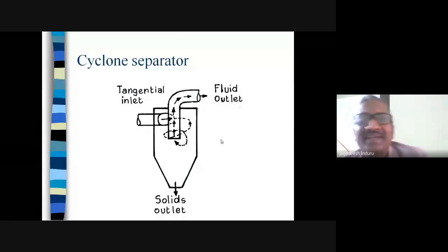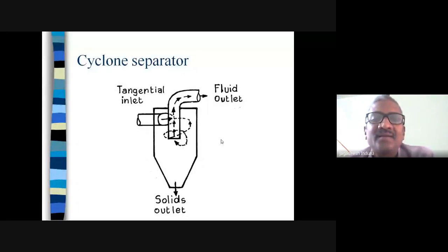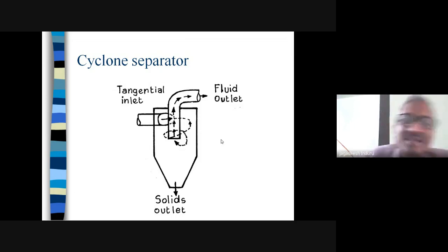The advantage of this equipment is that it does not have any sieving surface like a screen or a sieve. That is the reason it won't have any blockage of the sieves or the screen. That is the major advantage. Because the sieve and screen are not there, but still we are getting a separation by size. That is actually the beauty of this equipment.